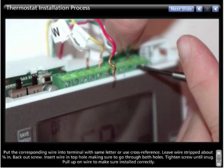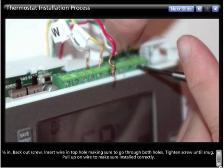Now, put the corresponding wire into the terminal with the same letter or use a cross-reference. Next, leave the wire stripped about a 1/4 inch back. Now back out the screw. Insert the wire into the top hole, making sure to go through both holes. Now tighten the screw until it's snug. Go ahead and pull up on the wire to make sure you installed it correctly.